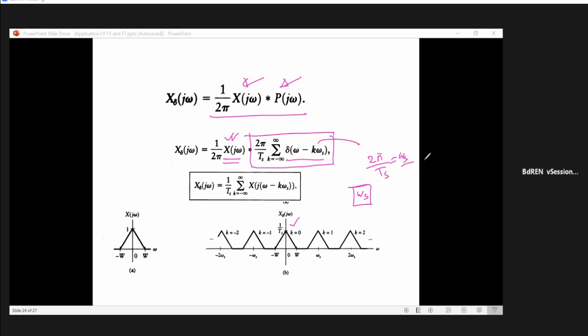You understand the thing? Yes, sir. Then what is happening? The spectrum of your original signal is shifted to the locations of the sampling frequencies in either direction, okay? Again, you see that negatives are there mathematically. Now you see that if this is the case, then this spectrum and this spectrum are separated in frequency, isn't it? They have no overlap region. Is there any overlap region? No, sir. Then after processing it, you can easily extract your signal back from this discrete version to the continuous version, no problem, by filtering.